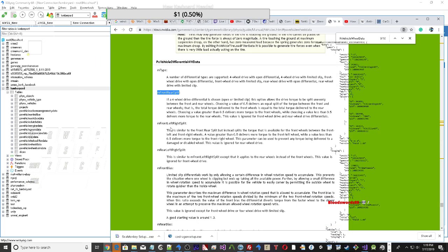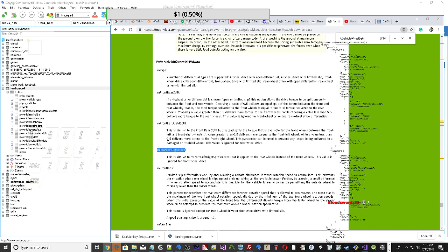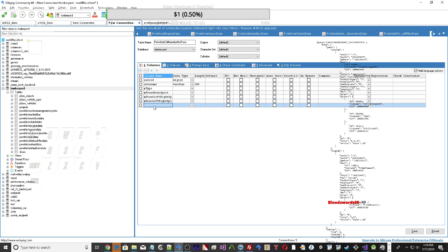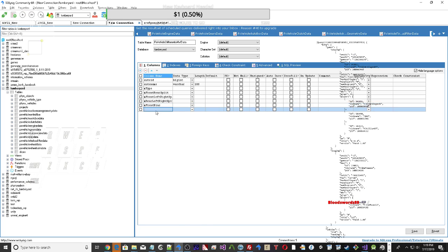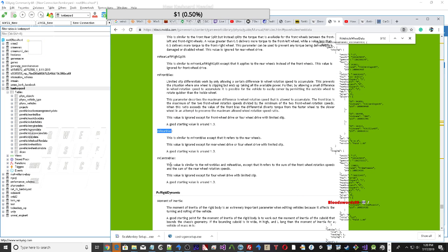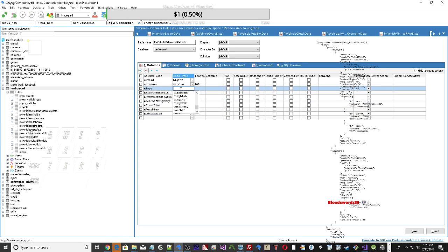In addition, if serialization is required, the PxSerializationRegistry specified for PxInitVehicleSDK needs to be passed to PxCloseVehicleSDK. If vehicle serialization is used, then this must be called before closing the PhysX extensions.